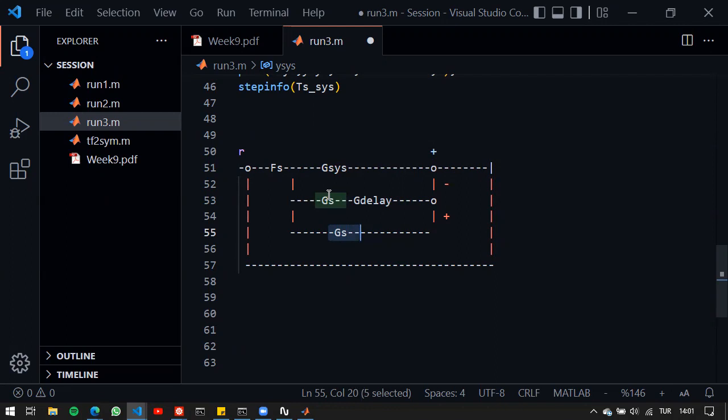This is actually a special type of control. This is called internal model control, but this is just for delay systems, so systems with delays. And here what we do is we are basically using a model matching controller strategy. Remember that we were using the model matching controller where we define a closed loop and then we acquire the controller that does the job.